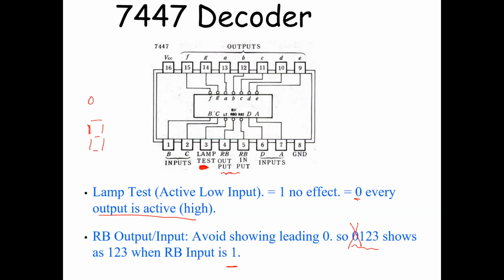Okay. Other than that, we have BCD. That will be connected to your decade counter, the 7490 chip I showed you. And then this is going to be the corresponding output. So this wiring has been done for you. All you have to do is connect the LED display to this output. This goes to the 7490, and this goes to the LED display. So depending on what you supply to the 7490, you will see the corresponding LEDs lit on the LED display. Okay, that's all to it. Again, there's a VCC and ground because it's an active circuit.